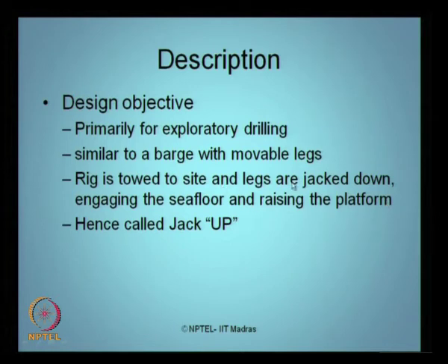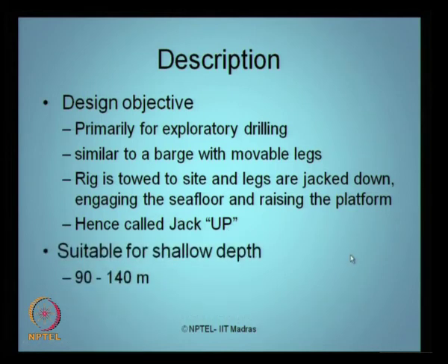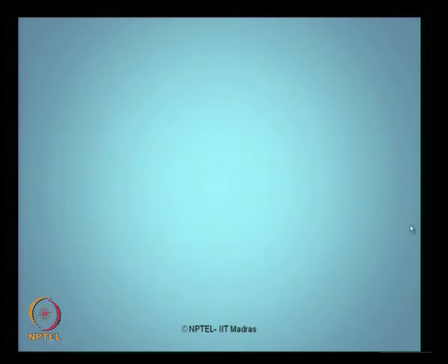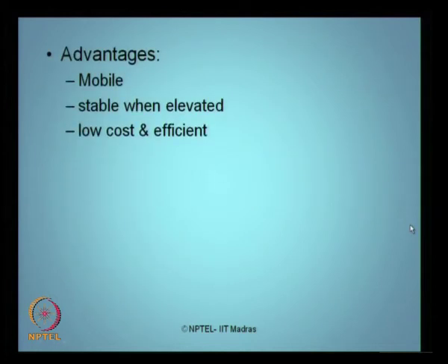Since the legs are jacked down and the platform is raised up, we call this jack-up rigs. They are suitable for shallow water depths up to 140 meters, essentially used for exploration drilling only, not for production. So these platforms do not have storage capacity.